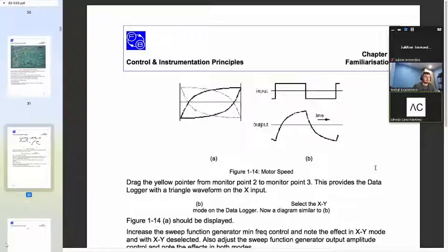So notice how these things are plotted. On the B side, you are plotting the voltages against time. For example, at the input at the top, you are plotting this square wave against time, and then the output at the bottom behaves just like an RC circuit that you know about, and this thing is plotted against time. You see the horizontal axis is time, right? You see what I'm saying? So now imagine, instead of plotting these two voltages against time, imagine plotting the voltages against each other.